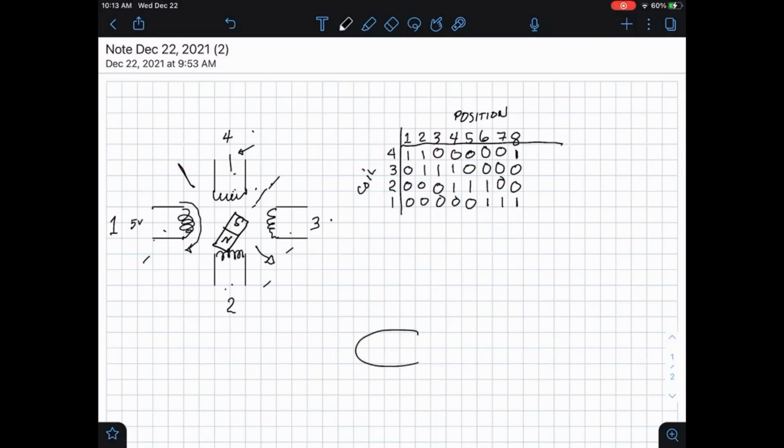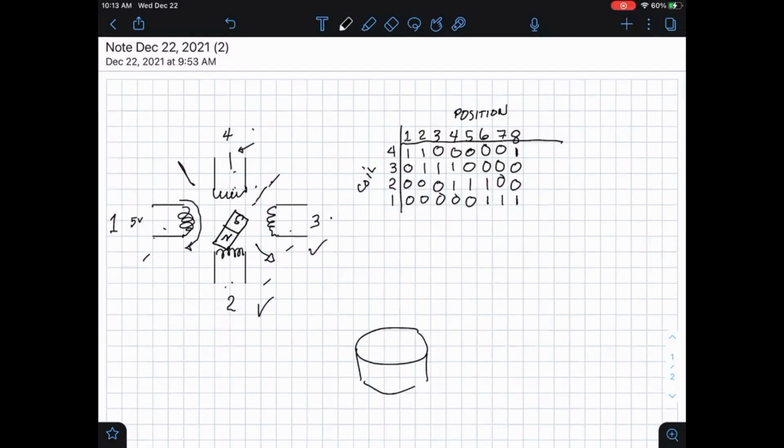So if you look inside a stepper motor, there would be an assembly where there are these 4 electromagnets which can be turned on and off by applying a voltage. The shaft is connected to a permanent magnet, okay, whose orientation is controlled by the coils around it, by the magnetization of the coils around it.